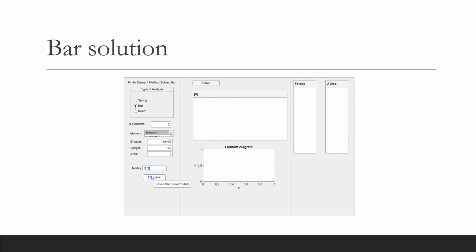And it's important that every single time you put the values in the same type of measurements. You cannot put a length in feet when you are using PSI, which is pounds per square inch. If you're using PSI, you have to use the length in inches and the area in inches too.